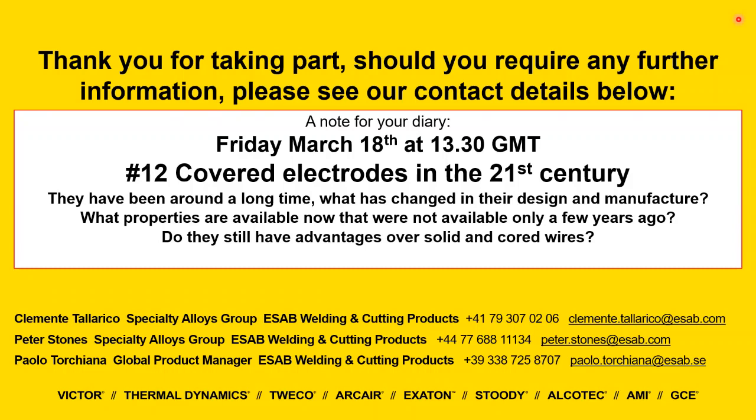Do you want me to say that, Clemente? Yeah, absolutely. You've got a power source that can deliver 1250 amps. So providing you select the parameters that will fit, then absolutely fine. There's no special power sources for electroslag or submerged arc. It's a power source. And the difference is really in the use of the flux, the different types of flux. So select a process whereby 1250 amps is enough. Does that make sense, Clemente?